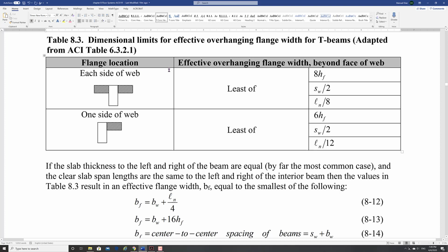Because this will be your beam, that would be a little different, unless you have beams that are not the same length, and then you have that problem. But other than that, this will be the same, so you can do l_n/4. So l_n is the clear span of the beam. Then here you have 8h_f on this side and 8h_f on the other side. Again, unless you change the sizes of your slabs, which could happen, though not very common. Normally you would have b_w plus 16h_f.